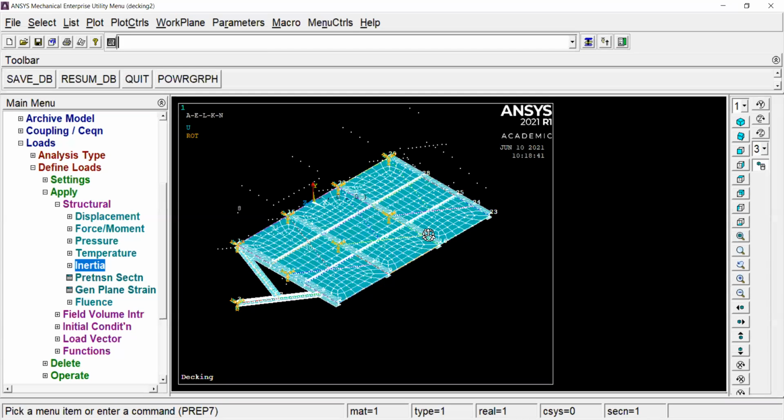So this is how you would go about applying your loads. If you're designing a bridge or a billboard or the crane even. The crane, you probably wouldn't have any plate elements. You just have all beams, so you just apply a UDL or a point force. If it's a truss structure, you can apply a point force. Point force is the worst case scenario. So for you, a point force would be worse. But if your design involves plates as well as beams, it's probably best to apply a face pressure.